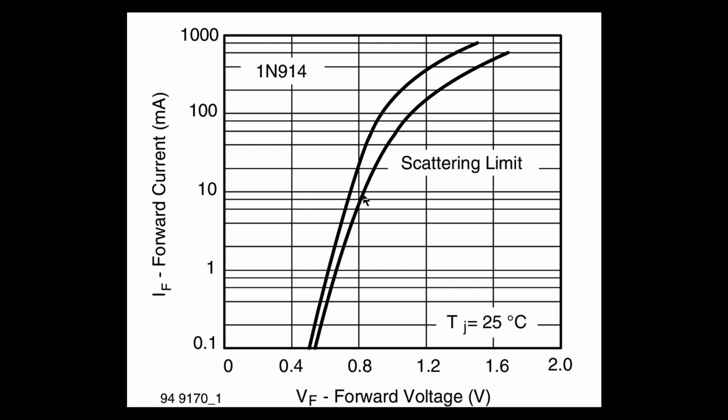I hope this makes sense. Think about it this way. If we went up to 1 amp, wow, look at how much difference those same diodes would show me. So it'd be easy to see the differences between each one of them. So down here, it'd be a little harder because there's not going to be much difference between them. So as we go up in current, this gets wider.